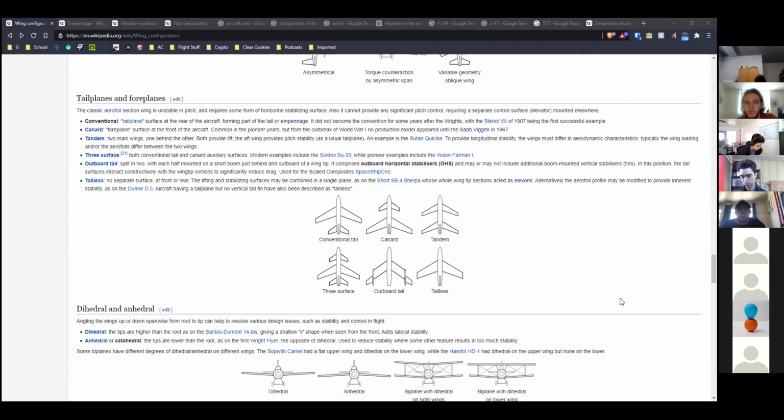Whereas with foam, the whole thing is usually solid, or at least it was solid, and then sometimes you cut the middle out. But it's harder to do compound 3D shapes. It's a lot easier to do a constant cross section, because the foam cutter uses a heated wire to cut through the foam. So you have to be able to connect the 2 points, which you can do in a tapered wing. You just have to have the computer do it, I guess.